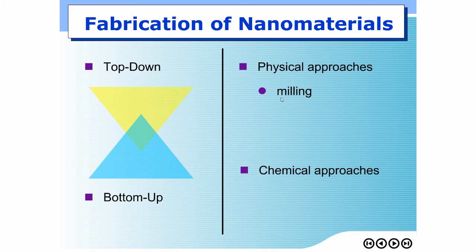Okay, you can do evaporation and quench. Just evaporate your reactants or evaporate your solid, sublime into vapor, and quench them quickly. You will end up with nanoparticles. These are considered physical approaches because inside the technique there is no chemical reaction at all.